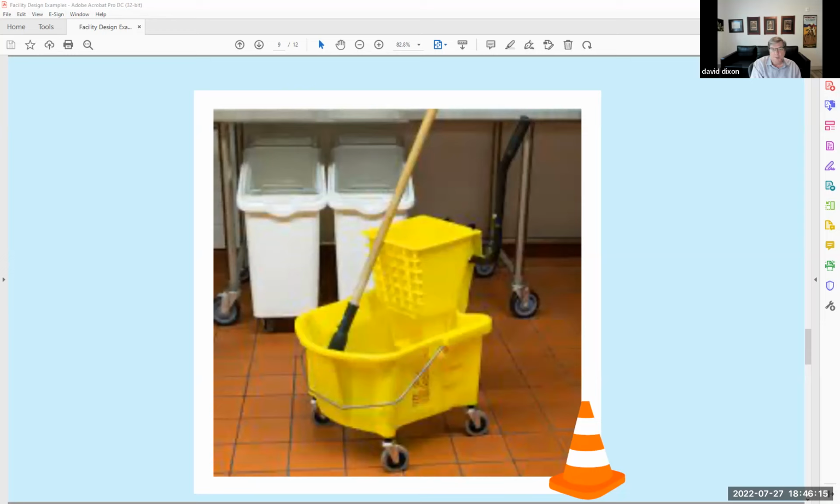Go ahead, David. Mops are bad. Squeegees, a free draining floor made with an impervious polyurethane or epoxy resinous flooring coating, not a paint, up to a quarter inch thick, but free draining to a spot drain. You use your squeegees to squeegee the water, it dries out. No mops, please, no mops.